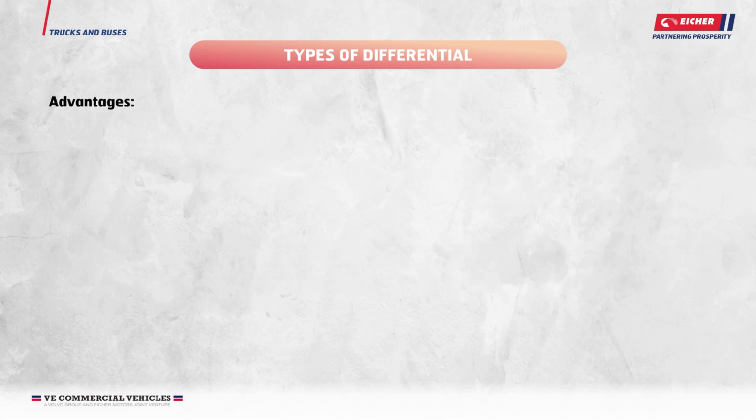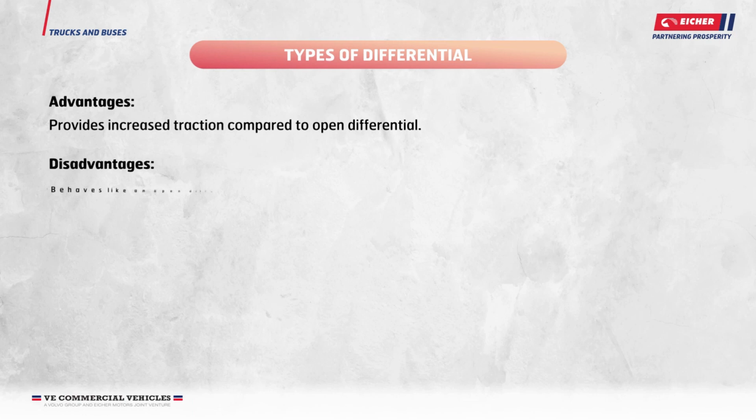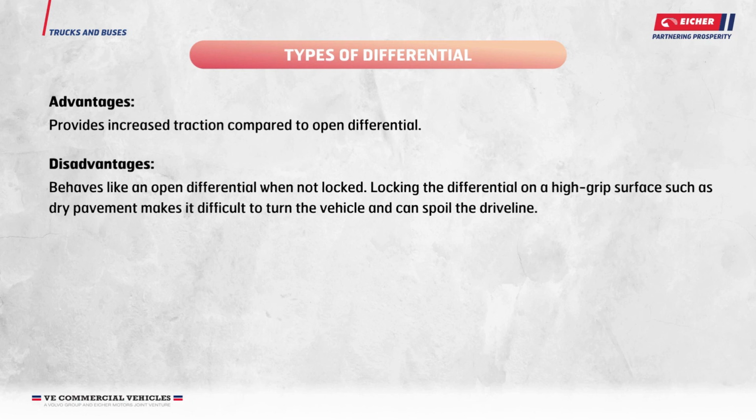Advantages. Provides increased traction compared to open differential. Disadvantages. Acts like an open differential when not locked. Locking the differential on a high grip surface, such as dry pavement, makes it difficult to turn the vehicle and can spoil the drive line.